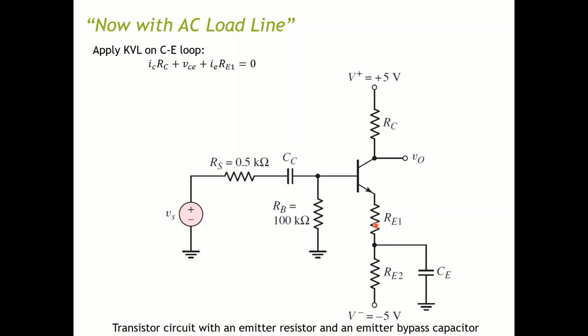And also in AC condition, you have to remember to ground your VCC. That's another thing. You can relate that to your small signal equivalent circuit to see how it works. Now you use this hint over here. You have IE equal to (1 + beta) over beta times IC.